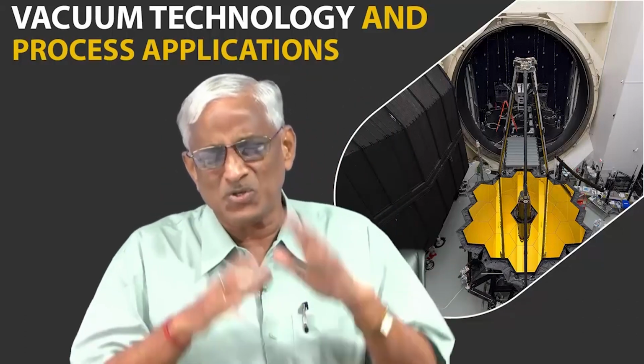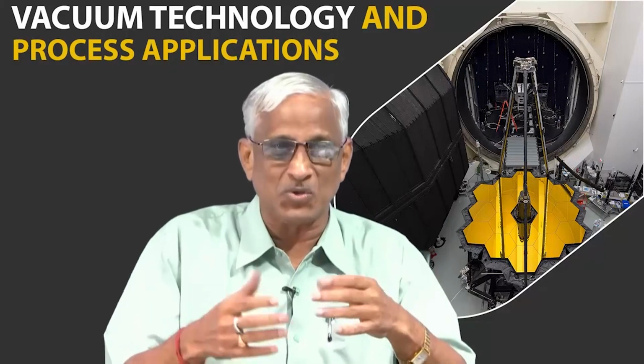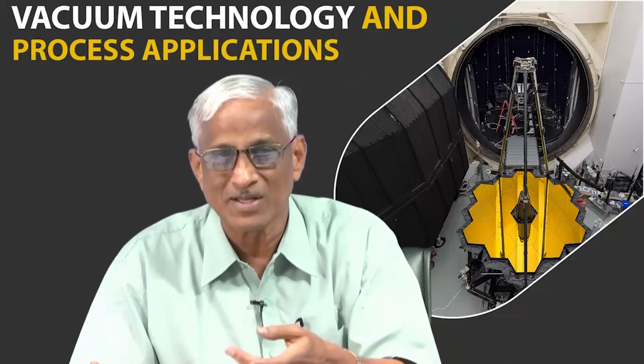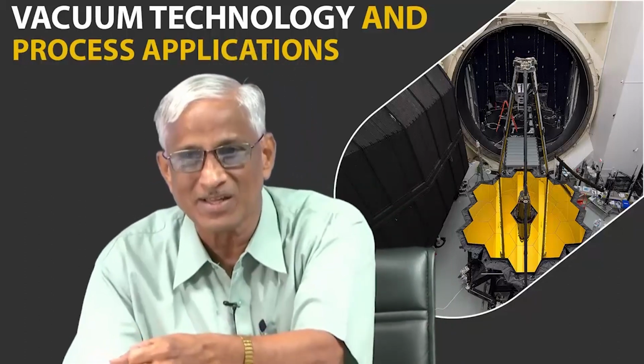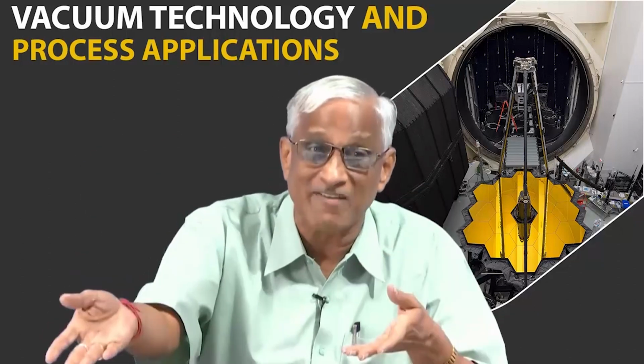In vacuum technology, you should guess, it can be that, it may be this. I have seen a good student, because of continuous practice, able to solve a problem in 2 hours, and a dull-headed fellow will take 2 days for the same problem, because he will not attack it in the right place. He knows that something is happening, vacuum is not coming in the system. You should have tightened something, you should have tried something, and he says the diffusion pump is not working. He has forgotten to switch on the water circulation, or forgotten whether the valve is open or not, or he has used a bad vacuum gauge available in the laboratory. So, the gauge may not be working.